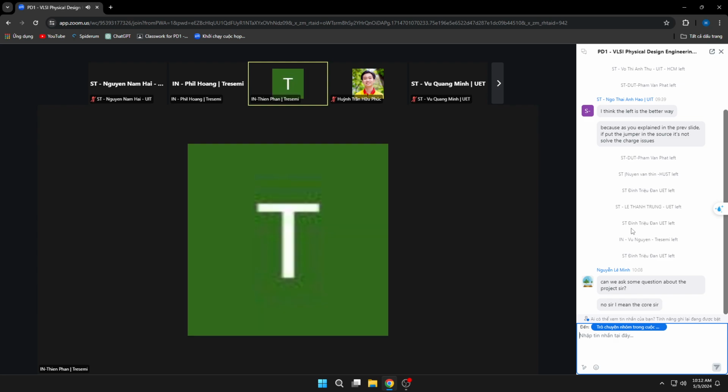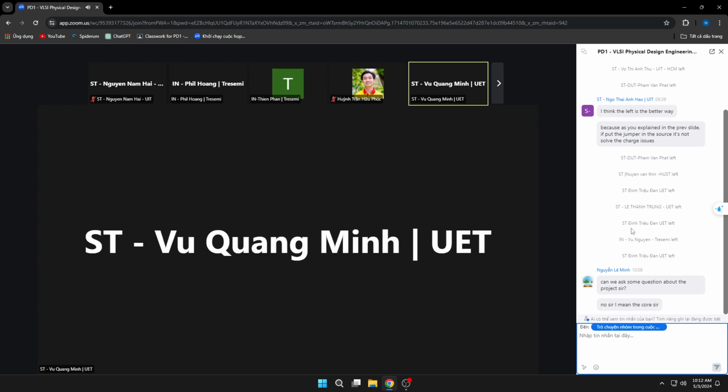So okay, let me try to understand the reason. It seemed like he tried to run multiple experiments, that's why he has multiple copies of certain files, and wants to point to different files for multiple runs. Is that right? No, I just run Innovus in a different place. So there are some paths in the MMMC file that do not match my place, so I have to change them in order to import the design.